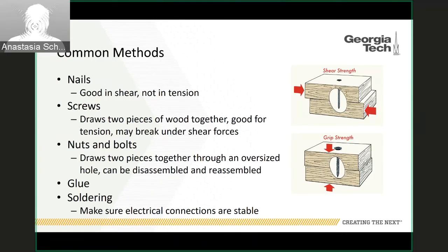There are also nuts and bolts. Bolts are similar to screws in that they draw two pieces together, but instead of drilling partway through the second piece of material and having it nested like a screw, when you use a nut and bolt, you want to drill an oversized clearance hole through both pieces of the material, and then you fasten the nut and bolt. This allows you to disassemble and reassemble as many times as you want, whereas the screw probably only has a certain lifetime before it stops biting into the wood threads.